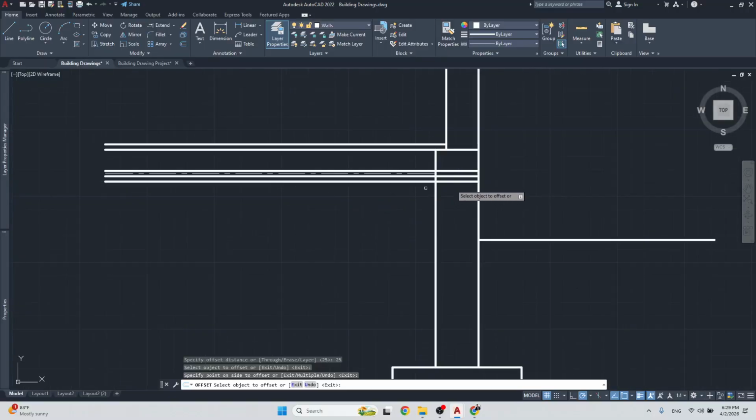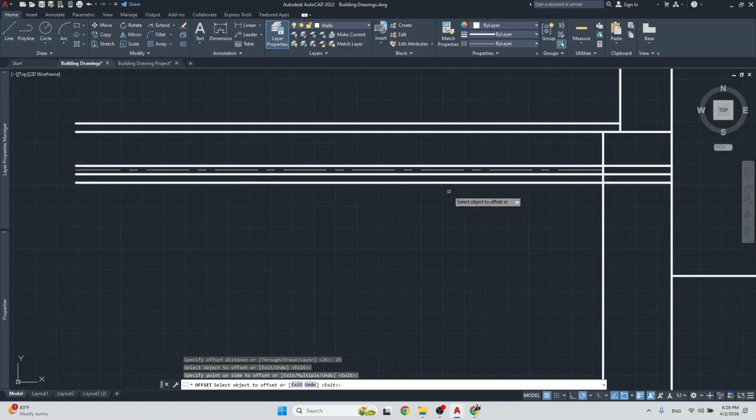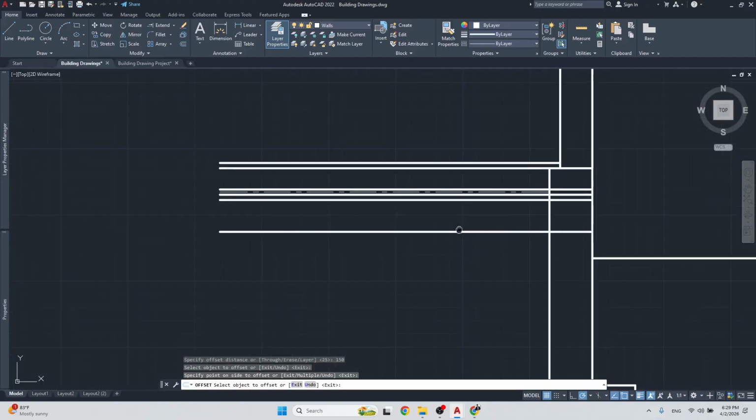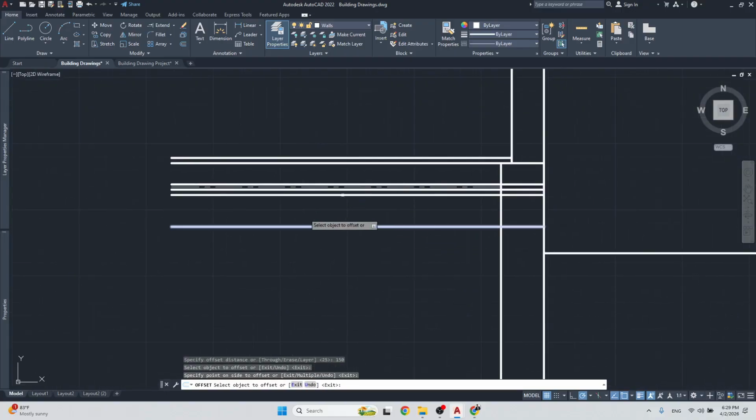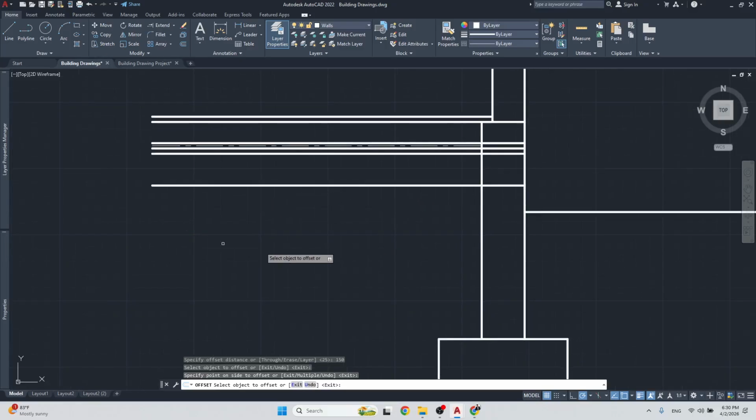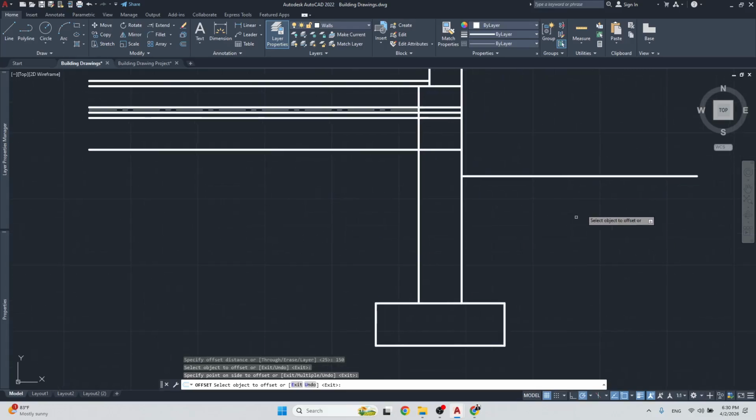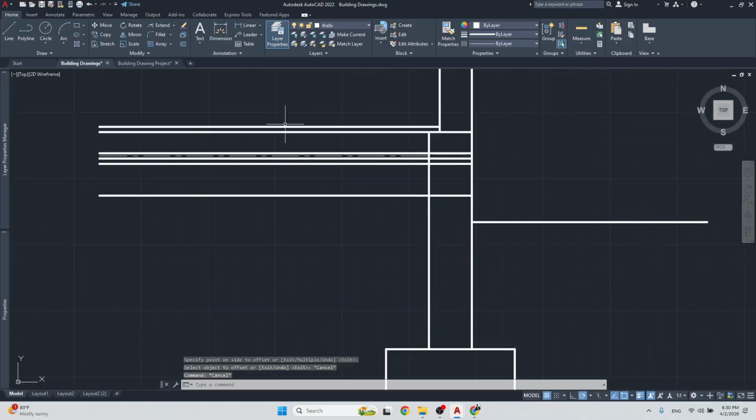Our sand blinding is just a mix of concrete. This is going to be about an inch, and then underneath of that we're going to put 6 inches, which is 150 millimeters, of our hard core. All right, which is going to be bigger rocks, gravel, and so on. And then underneath of that we're going to have our earth, compacted earth, under here also. All right, so that's all we need.